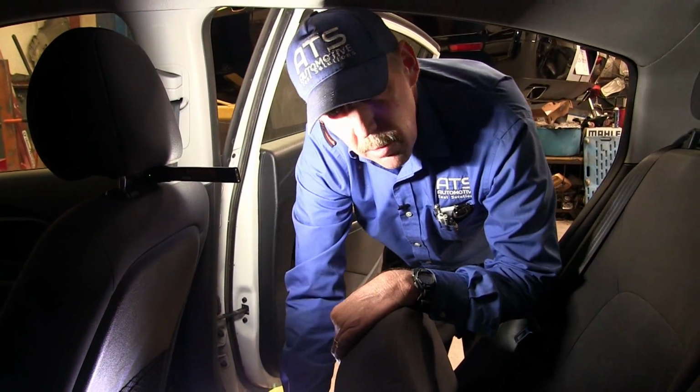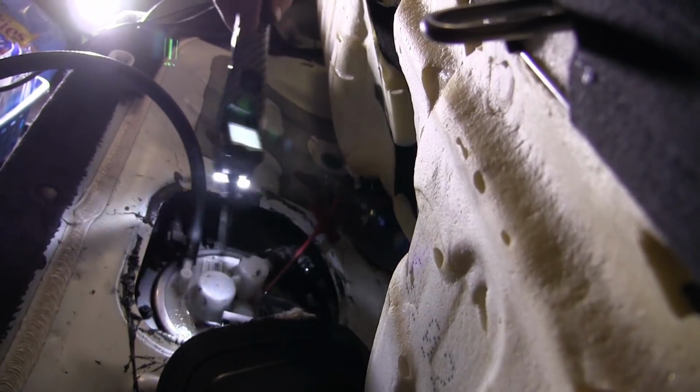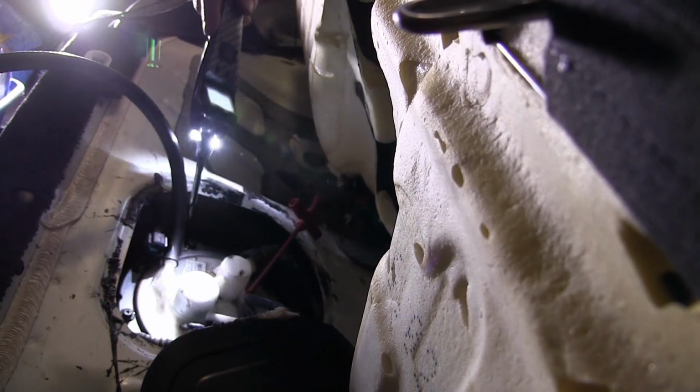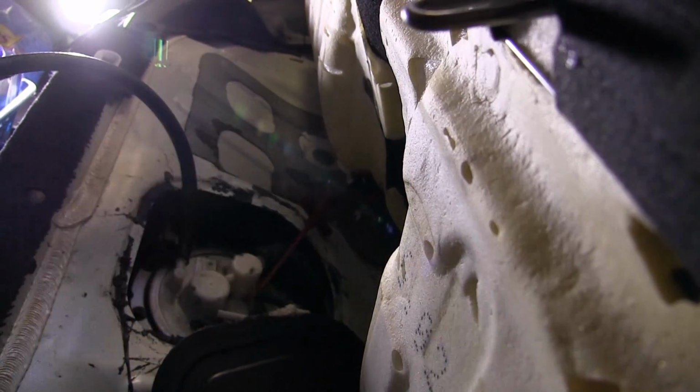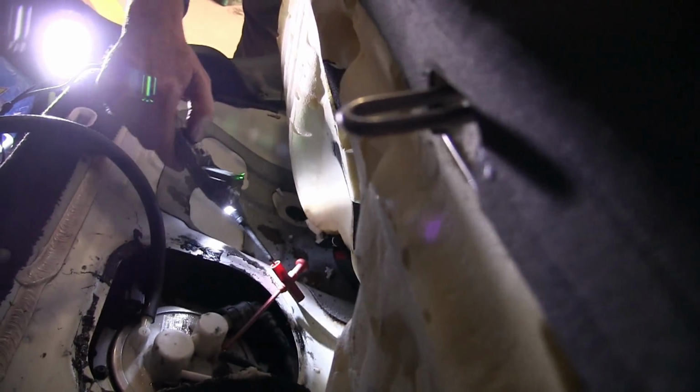Okay guys, let me show you what I set up to test this vehicle with. This is the second new module that's been in that car, so I don't want to take it out because it doesn't have a problem. I found the power wire, and I'm going to feed power directly to the pump, and I took the line that goes up to the engine and I pulled it off of the module. Now I'm going to feed the fuel directly into a measuring apparatus. So let's go ahead and